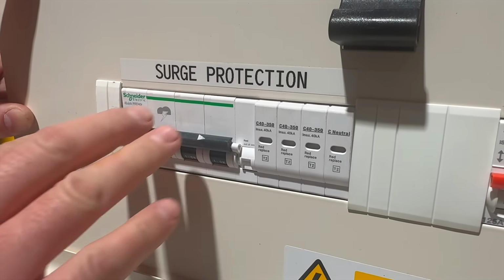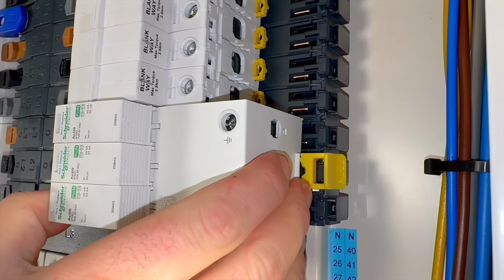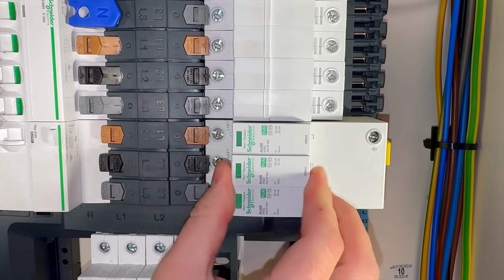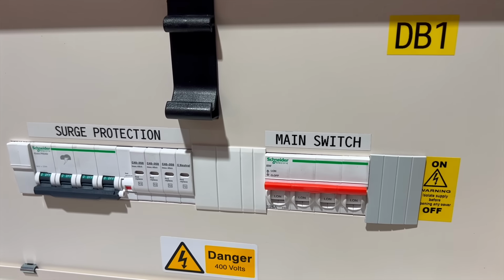Yes. Not because of a rule about boards, because cable lengths actually affect the voltage seen by equipment during surge events. So if you fitted an SPD at the origin and assumed that that is enough to protect the entire installation, well, it's probably not. And that's not because the device is faulty, but because surge protection is about system design, not just product selection.